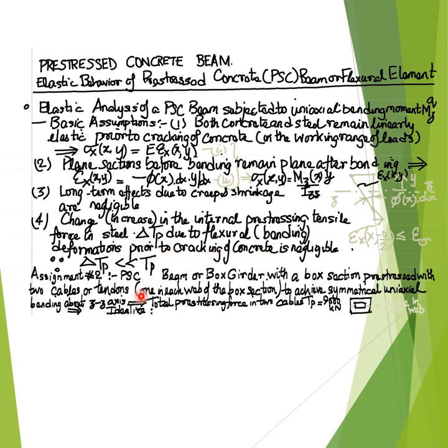In other words, the change or increase delta Tp in the internal pre-stressing tensile force in the steel as well as concrete in the pre-stressed concrete beam due to the flexural or bending deformations is negligibly small.